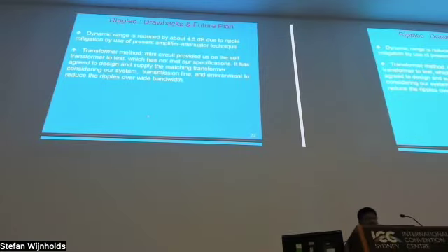So the drawback, as I said earlier, of this attenuator method is dynamic range reduction. So for this, and to achieve better ripple reduction, we are going for a transformer method. We have used an off-the-shelf matching transformer from Mini-Circuits, but it has not met our specification.